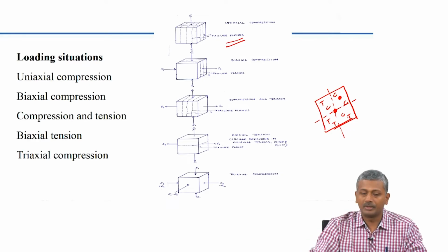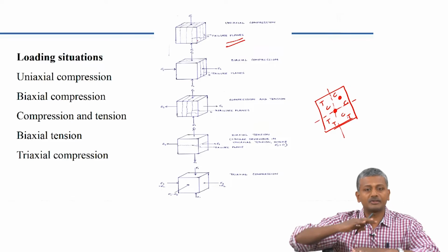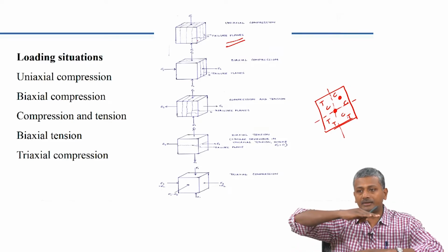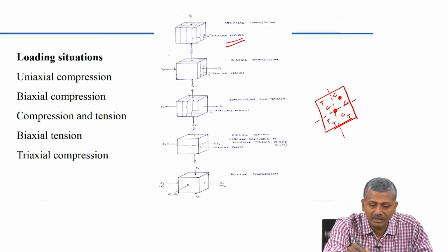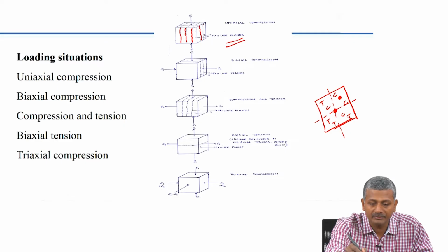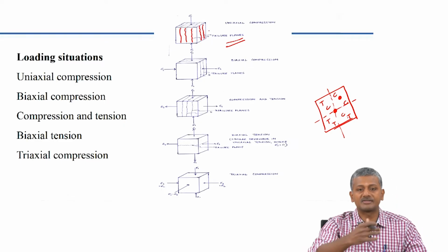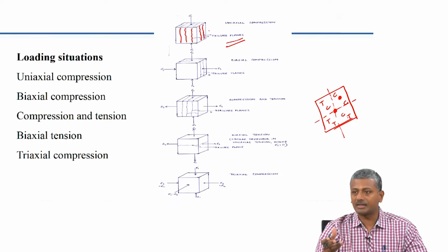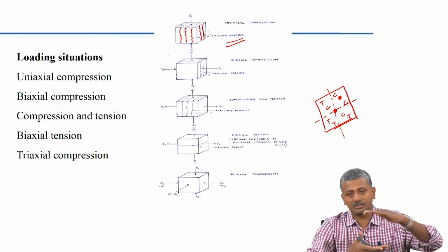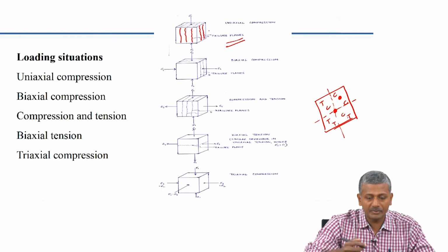Concrete is bulging outwards. When that happens, assuming there is no friction between the platen and the concrete, you get perfectly vertical cracks along all faces of the cube when you do a uniaxial compression test. Now, this is a very ideal case of fracture. You probably do not see it at all in the lab because there is sufficient friction between the platen and the cube. What happens when you have friction?